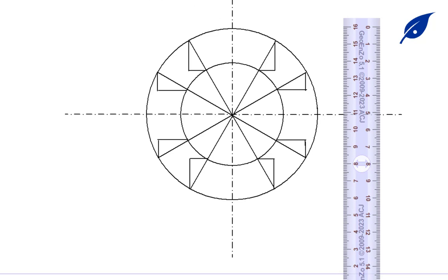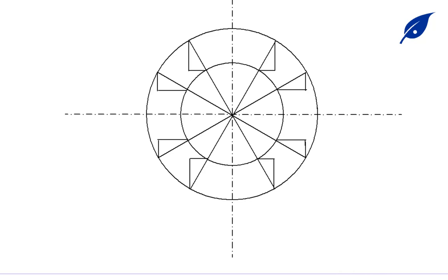So the next set of things that we're going to do is we'll mark each of these points where they are perpendicular. That's the 90 degrees there. We'll mark those points. Those are the points of our ellipse, where we're going to draw our ellipse. So looking at it, we've gotten these first 2 points, then we mark this point. Remember, we did not draw any perpendicular line there, but that's a point for our ellipse.